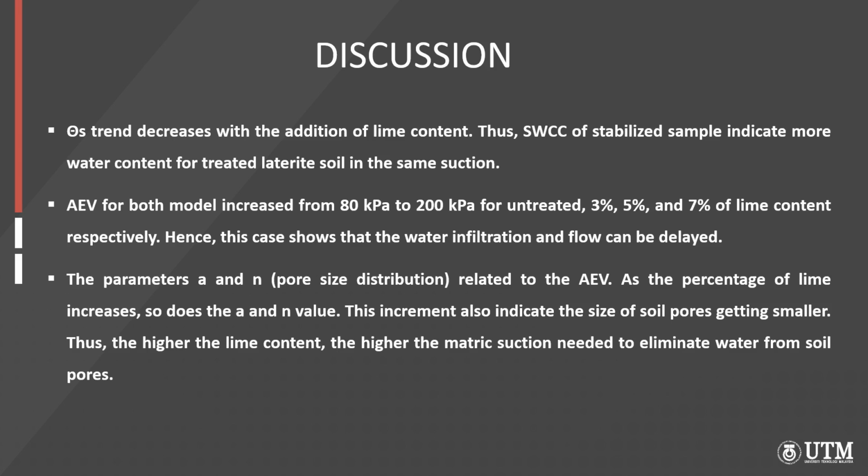Thus, the SWCC of stabilized samples indicates more water content for treated laterite soil at the same suction. The AEV or air entry value for both models increased from 80 kPa to 200 kPa for untreated, 3%, 5%, and 7% of lime content respectively. Hence, this shows that the water infiltration and flow can be delayed.